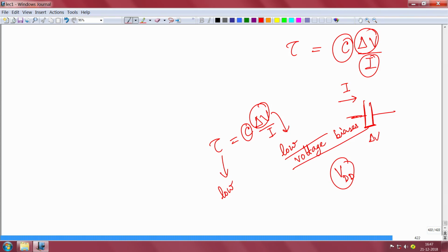And with continuous shrinking of these devices, you probably have known this, and I probably have told this in other classes, you are shrinking the device dimensions both laterally and vertically. So, which means the gate length is reducing, but along with the gate length you also have to reduce the dielectric oxide thickness, because you need to maintain an aspect ratio. Your thickness of the gate dielectric also has to reduce. I told you about the constant field scaling, constant voltage scaling. All the device dimensions are shrunk in such a way, including doping.